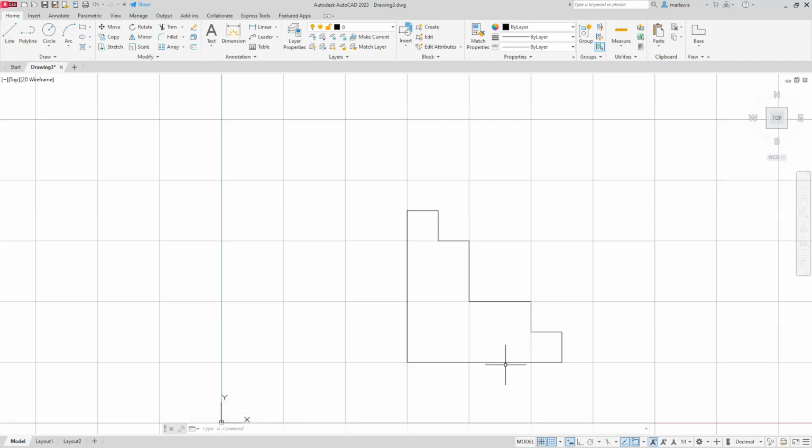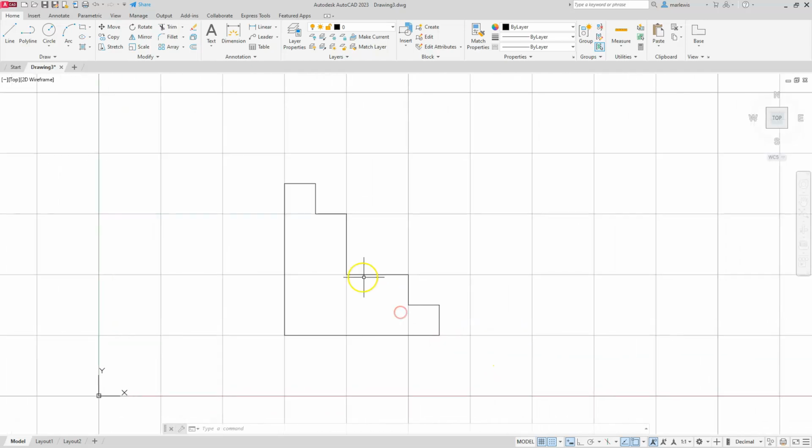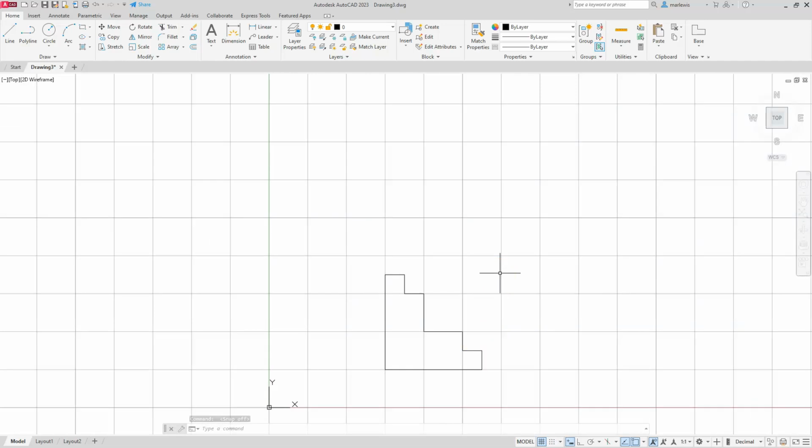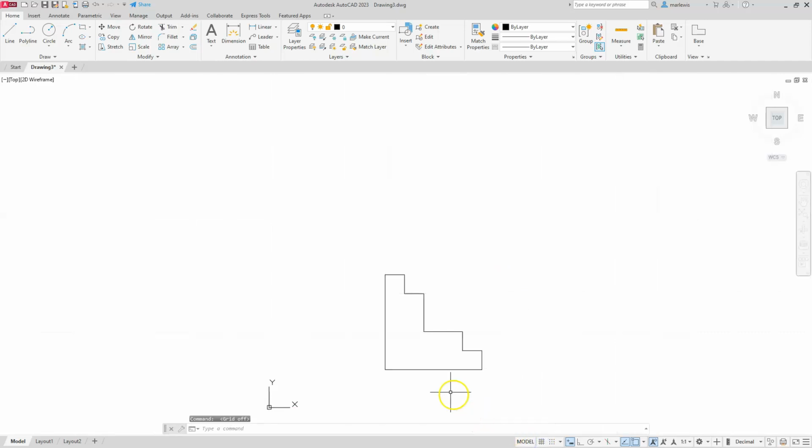Alright, so using a grid on this one is very useful. It'll stop me from having to actually punch in things. But in some rare cases, these numbers will be different, so you can physically overwrite those numbers just by typing them in. But in this example, it's a lot easier just to turn on our snap and turn on the grid. Now, one thing I want you to remember is that once you're done using that snap and that grid, go ahead and turn the snap off at least. That'll save you from the next time you start doing something else and it is snapping all over the place. So I always like to turn that back off, and I really don't use the grid that much, so I'll typically turn that off as well.